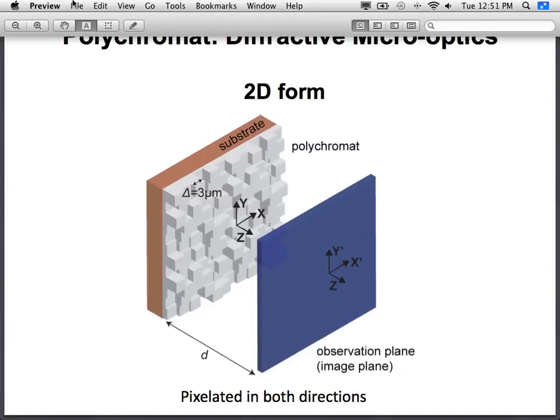They almost look random, but they're not. They're very specific. Each square has to be a specific height to get the right wavelength. Yeah, right. Depending on the height profile, it will create a specific diffraction pattern. If you change the height profile, you'll get a different diffraction pattern, so you have to design it to get a specific spectrum splitting.